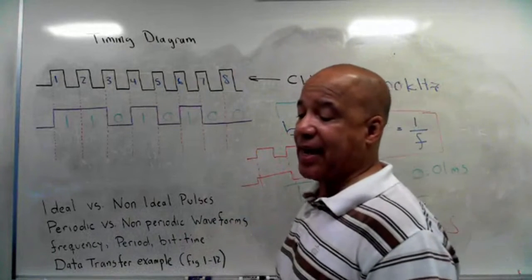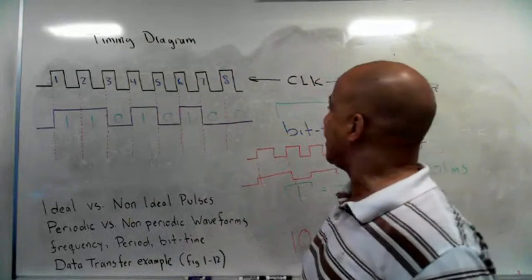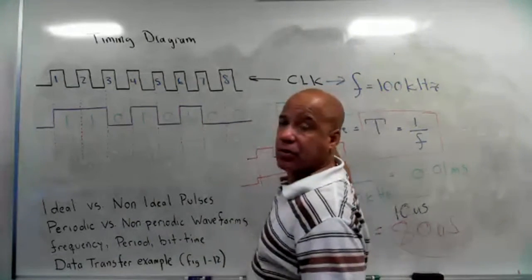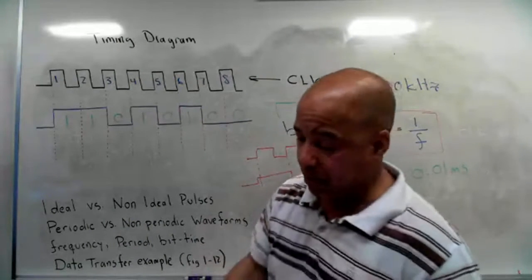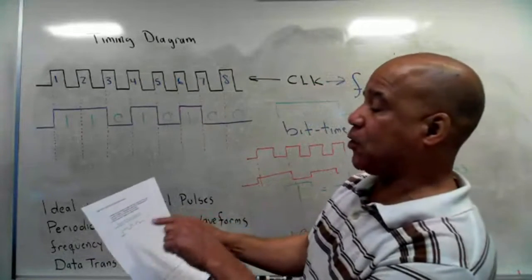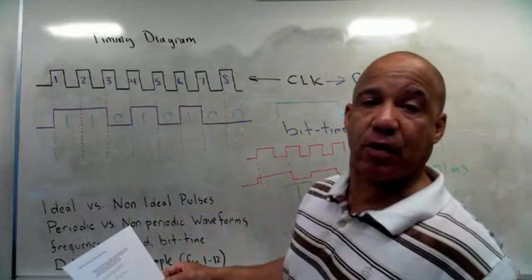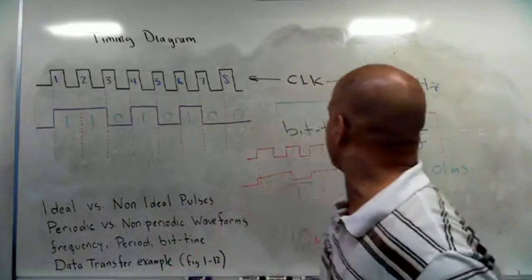And it says indicate the sequence of the bits. So it looks like this bit is going out first, that 0, but that's not what they tell you here. It says the leftmost bit is the first to be transferred. Now that's important that you understand that.